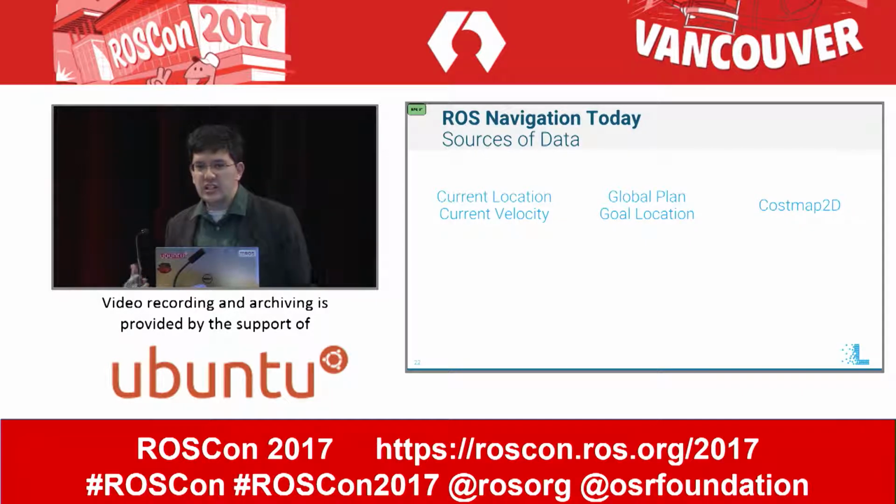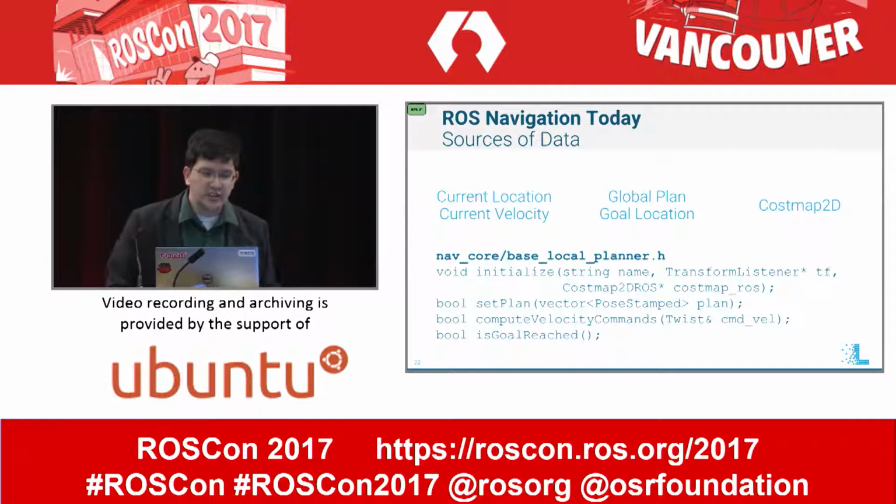First, if you look at the inputs that I talked about to the system, we have the robot's current location, its current velocity, the global plan, the goal location, and the local cost map. And if you take a look at the nav core interfaces for the local planner, some of the information is missing.